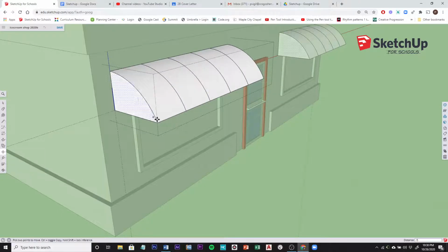So in between the first segment that I copy, this arc, and the last one, I have told it to copy that 5 times. So this is the first copy, 1, 2, 3, 4, 5 times, and an equal spacing. So it did the math for me. It divided that distance by 5. So now that this is divided, you should see each of these faces are separate.